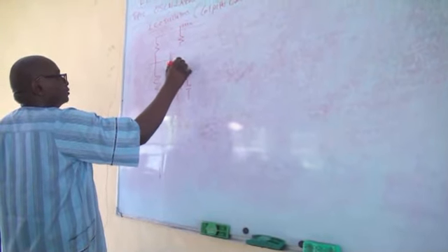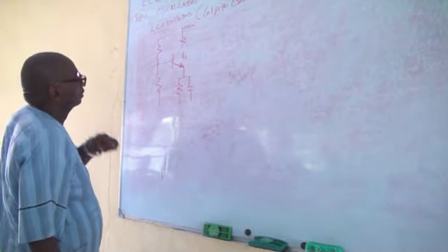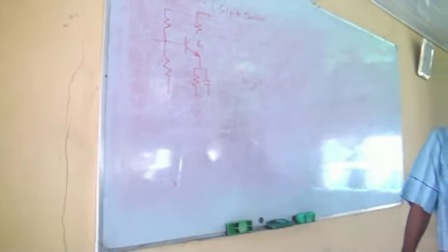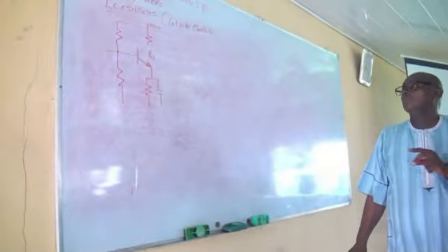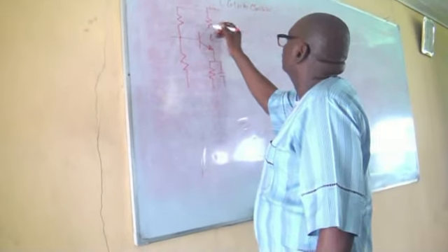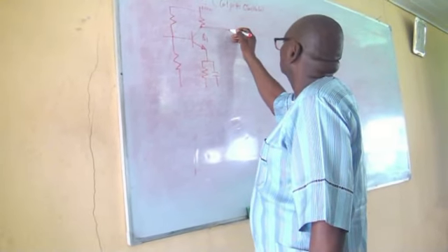We're using an NPN transistor, Q1. And we have a feedback loop. And this feedback loop is going to have two capacitors and one inductor because it's a Colpitts. So if the output is taken from here, which is from the collector, this is the capacitor.